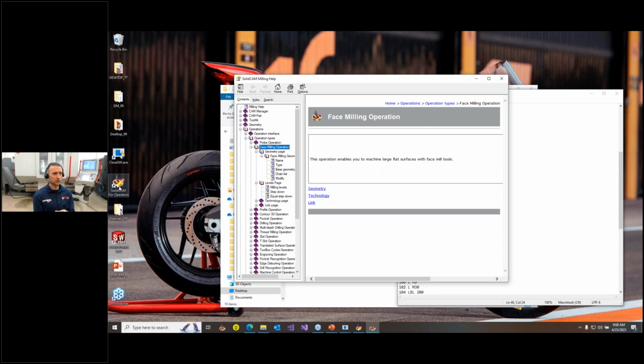And since SolidCAM for operators is the normal SolidCAM install, you can just go download SolidCAM, install it on a new computer, and I think you get a 30 or 60-day trial license with it. So any customers who are interested in trying it, you already have SolidCAM downloaded. If you got a computer on the shop floor, go install it. You got 30 or 60 days to show your users and the shop floor people that they can use it. All you got to do is take your SolidCAM part file and make it accessible for them to open.